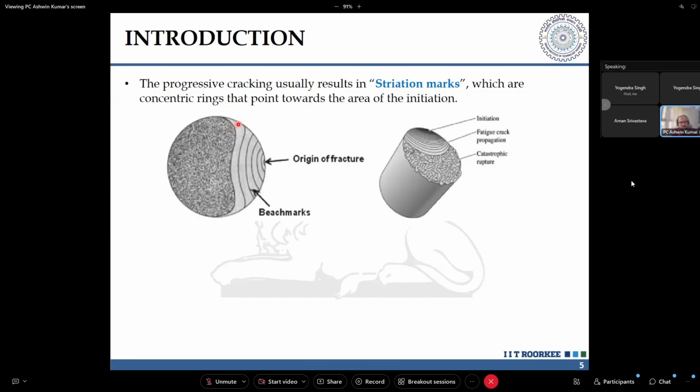So you have certain areas where the metal will leave its contact, and there will be a reduction in the tensile stress area over which the load acts. After the crack has initiated and propagated, the reduced cross-sectional area is what remains to carry the load. After a certain limit is reached, sudden brittle failure may occur.